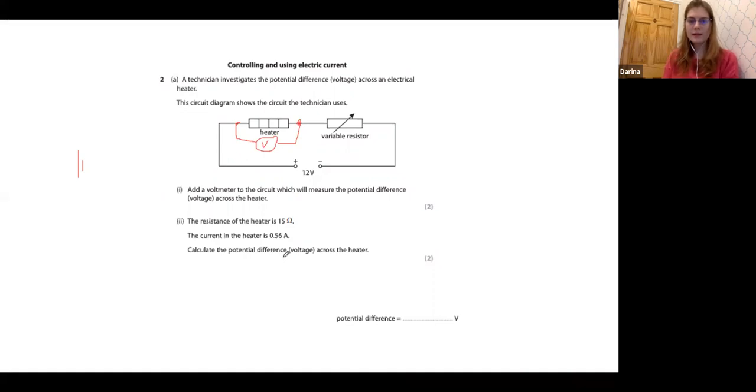Okay, perfect. Got quite a few right answers. Everyone, please do have a go and pop it in the chat. If you don't get it, then we'll go through it. Right, okay, well done everyone. Everyone who did got 8.4, which is the correct answer. So here, obviously we will be doing V equals IR. So you're doing 15 times 0.56, which is, as you said, 8.4 volts. Well done.